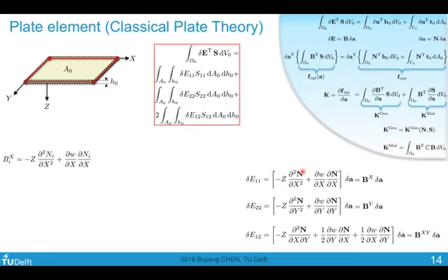This is simply plugging in the ith term of n, and then we would arrive at this expression. To facilitate our partial derivative operation with respect to nodal degrees of freedom, we replace W by the shape function multiplied with the nodal degree of freedom vector, and we write the indicial notation by Einstein summation convention. So we now have W equals Nj Aj.